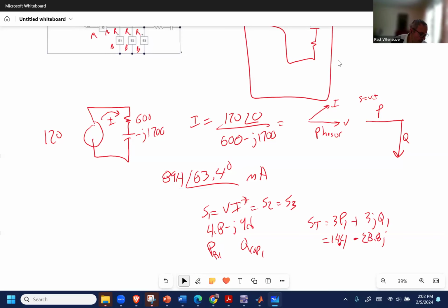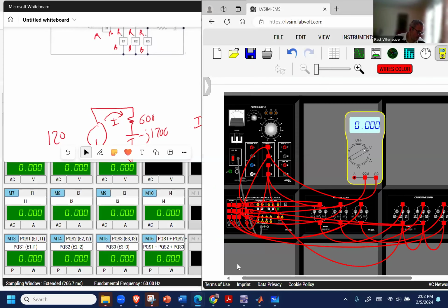So now we can go back to our circuit, and the voltage has to be 120 volts. We're going to turn that all the way down again, just to be safe. Flip our switch, turn it up slowly, and see our voltages all look about the same and our currents look pretty good. So we're able to turn it up pretty quickly because nothing looks out of whack. I take it up to around 120. That's close enough for me.